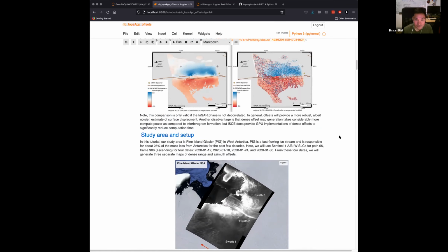I don't have that number off the top of my head, but it will be some fraction of the pixel size that you're using to do the cross correlation. So if you imagine full resolution SLCs for Sentinel, taking the upper bound of 14 meters in azimuth, then at best you'll get somewhere around 5 to 10 meters precision in your offset measurement. But that's the lower bound; as you get more noise sources in your images, you'll see that noise floor get higher and higher.